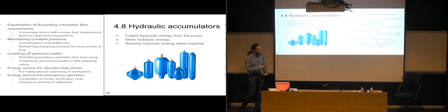And also it is, for example, used on ships for closing or opening bulkheads. If you suddenly lose power on the ship and your pump isn't running anymore, so you don't have any more pressure, they usually have designed accumulators that are capable of either closing or opening the bulkheads if need be. The bulkheads are these internal doors, basically, in the ship. So often it's, I'm a bit unsure. I think they are.